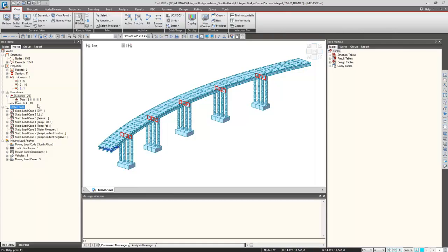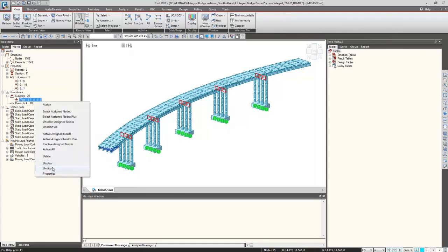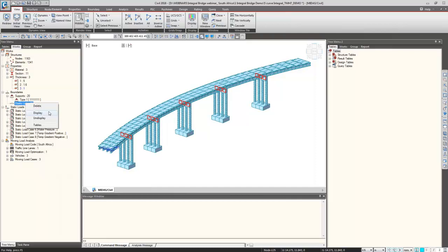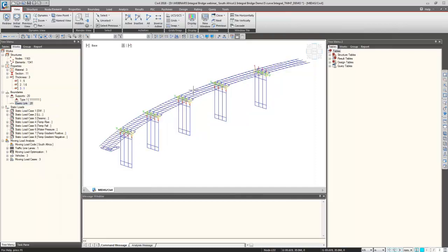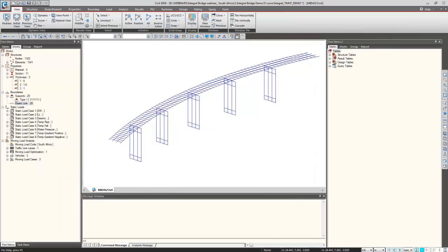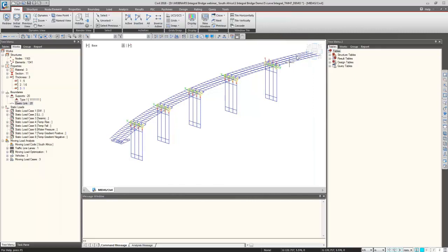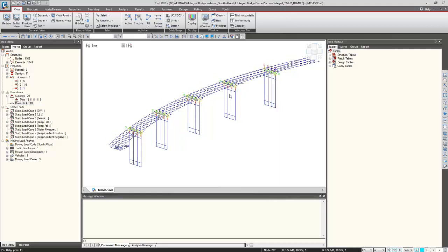And then you have these supports which are defined here at the bottom. Then you have these elastic links which are connecting the superstructure to the substructure here. Here we'll be modeling the abutments now. So these are all the loads that are being applied, and TMH7 is used for the moving load analysis. So for now, let's start modeling the abutments.